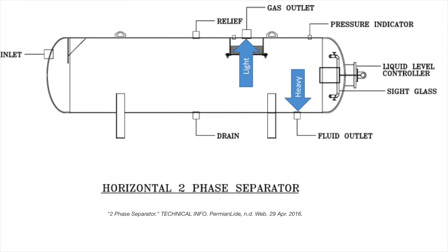There are two main types of separators used within the industry today. These include the 2-stage separator option as well as the 3-stage separator option, the latter option being used if you are producing water in your well stream. Like mentioned before, gravity is a key component within the separator because it allows the fluids to naturally separate out from its single original well stream condition. During separation, heaviest fluids end up at the bottom of the tank, while lighter fluids rise to the top.